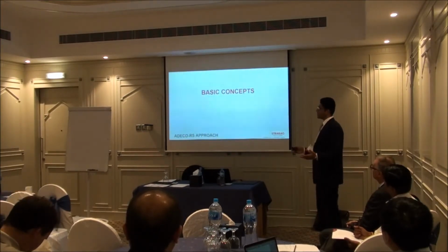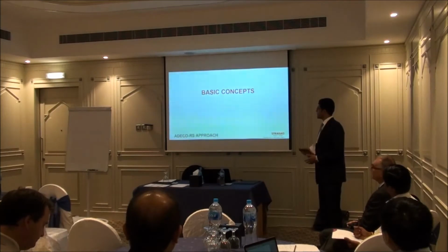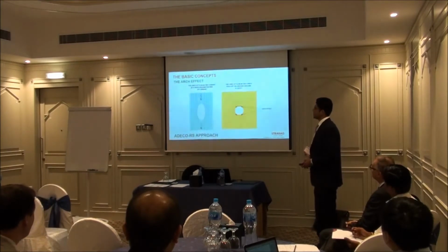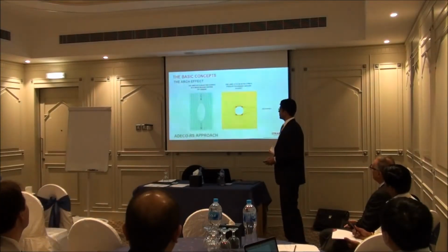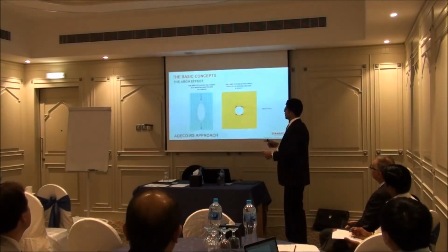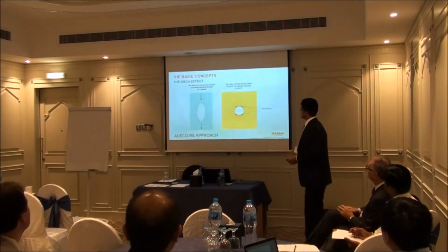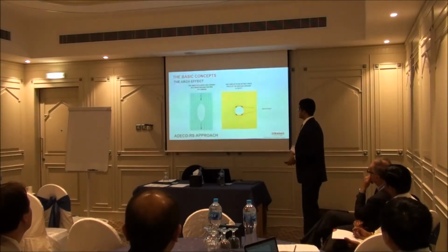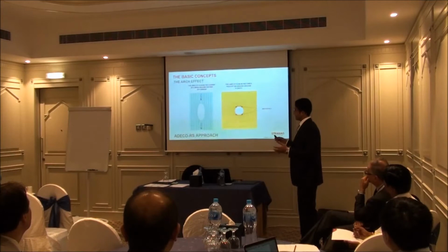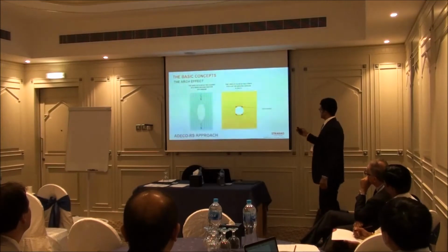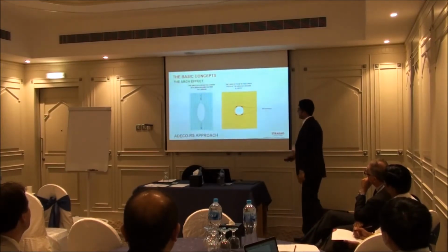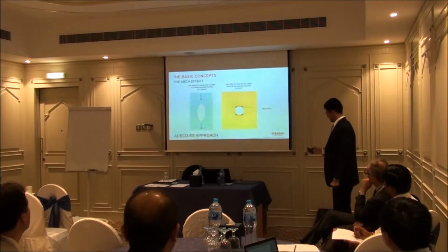The basic concepts, most of you will already be aware of them, so I'll just go through them for beginners like me in tunneling. Similar to the flow of water in a river, where the currents go around an obstruction like a pier, the stress conditions change or realign themselves when a cavity is introduced in a ground mass. When they realign themselves around the cavity, an arch effect is formed to stabilize.